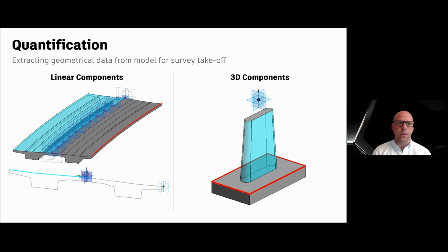The first one is tackling the linear components. So these components are created with the profiles. So here we can select the point. What you can see on the left-hand side is the marked point, and this point will later on represent an edge of this bridge. And the second possibility is to select the line, which will be extruded and will represent the face of the bridge. So in this way, we go from 0D to 1D, and from 1D to 2D, so 1 dimension higher.